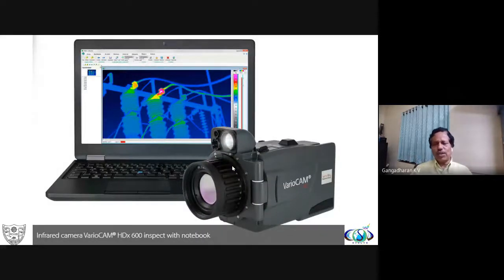Now, quite advanced technologies are available. We can even have the frames. I mean, you can take a video and see how things are working. Suppose you have a really huge farm where megawatts of power are connected directly to the grid, you can see the image there on the computer. It shows the contacts and connectors, where temperature differences are shown.